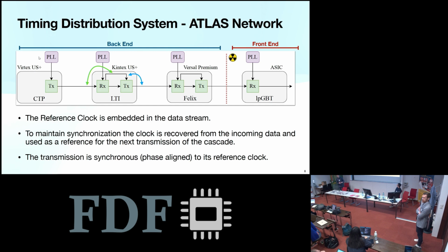Okay, so when I do the clock recovery and I use the recovered clock as a reference, if this is what you mean? Yes. So do you clean up the recovered clock? Yes, there is a jitter cleaner. The recovered clock goes in a jitter cleaner, and the output of the jitter cleaner is our reference for the transmission. And this jitter cleaner, to maintain phase determinism, is in zero delay mode. It's a Skyworks PLL, which has this zero delay mode, which guarantees fixed latency between input and output.